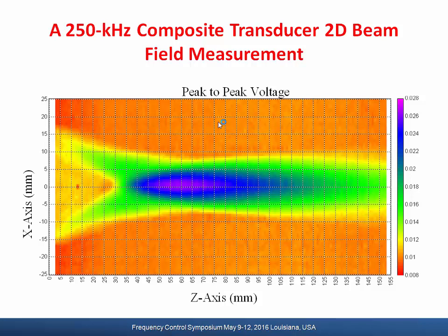And we try to avoid operation before 30 millimeters, because you can see there are double peaks, which is also called the double edge effect. If we have a target in this region, because of the double peaks, it is difficult to determine the position of the target. It could cause ambiguities.